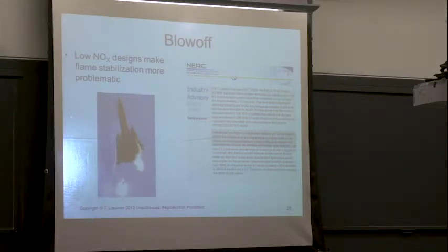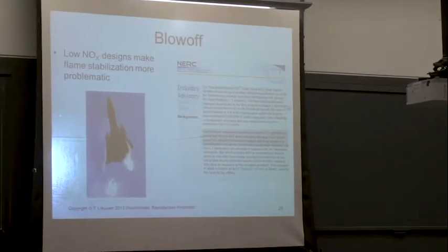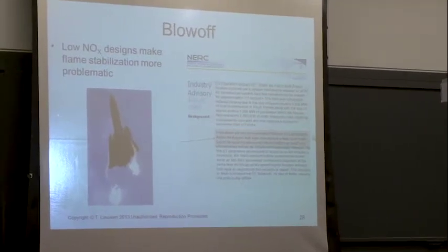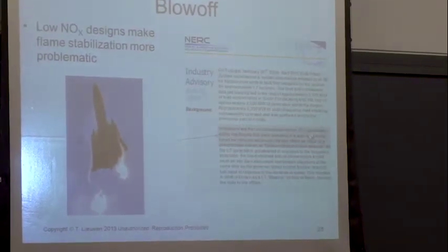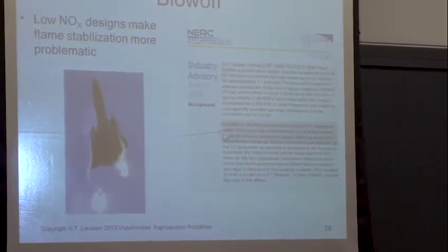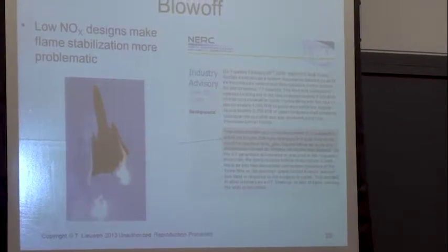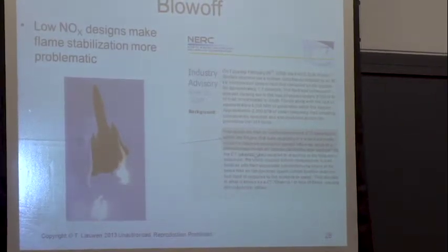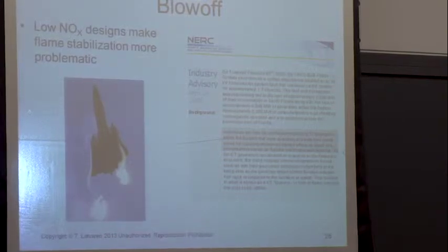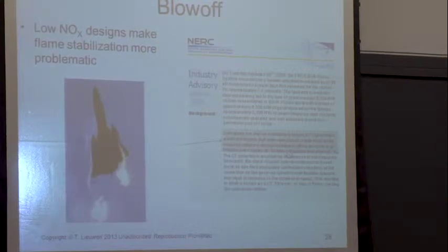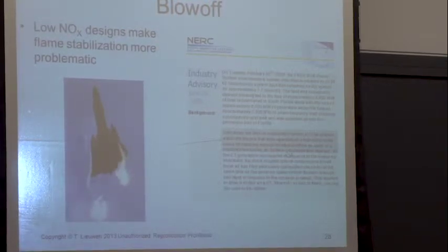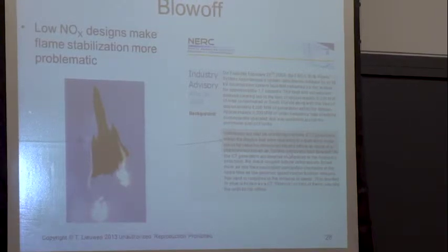But what's interesting is this one. This is the North American Electric Reliability Corporation. This is an industry advisory, and they're talking about a grid fault in Florida, and they say indications are that 6 combustion turbine generators within the region that were operating in a lean burn mode, which you all, being combustion people, know what that means, and they even give you this helpful explanation, used for reducing emissions, tripped offline as a result of a phenomenon known as turbine combustor lean blowout. So what that did was it led to a grid fault. When I see this stuff, I cut it out of the newspaper right away because my nerd combustion words don't show up in NERC advisories very often. So this was an interesting one.